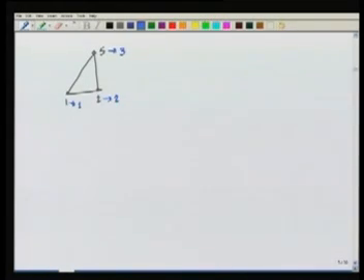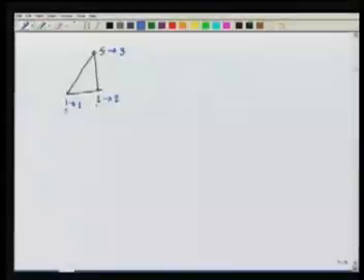So if I write my u_h in the element in terms of the global phi 1, phi 2 and phi 5, because these are the only non-zero ones, and v also in terms of the global phi 1, phi 2 and phi 5, which means my element only contributes to the global equations 1, 2 and 5 and to the columns 1, 2 and 5 of the global equations. This is exactly the way we have discussed it for the 1D problem.